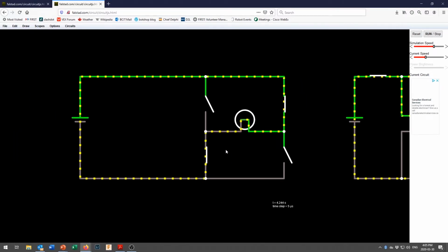just a switch-based H-bridge. Now keep in mind that the direction that the electric motor turns is based on the direction that the electricity flows through it. And right now we've got our electricity, positive current flowing out this way, coming down right through here, through the motor, turning the motor in this direction, counterclockwise, and then coming out through down here.